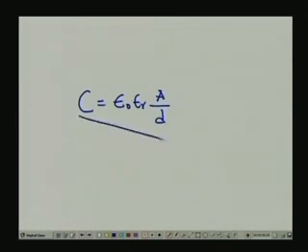You can see from this relation that C is inversely proportional to D. So, it is a nonlinear relation, because if you take a differentiation then you find it is nonlinear, right. But we can see that with the use of a simple op amp we can linearize it. This is very much necessary because in many applications we need this type of measurements.